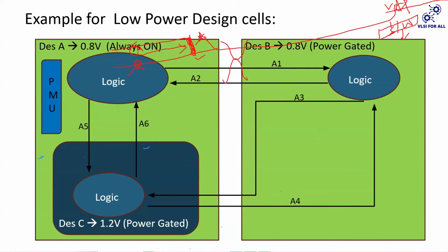The power switches will never be included for the signals which are traversing within the design. This is something done at power planning, where the switches are implemented in a daisy chain fashion, and these are implemented at top level. Whenever signals are going across the domains or within the logics, power switches can't play any role because they are not sending power, they are sending signals.